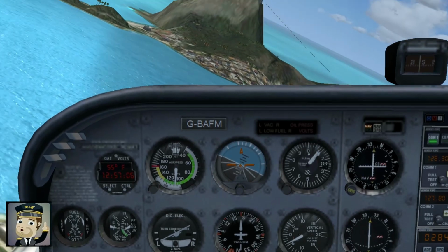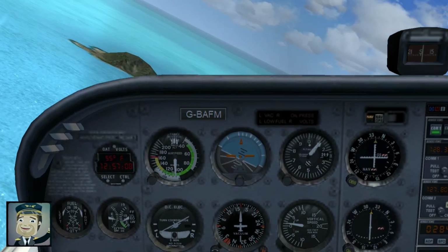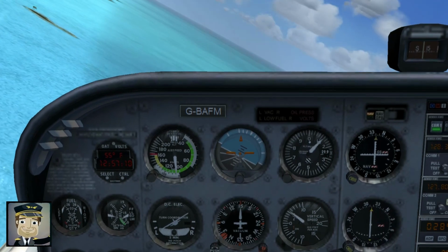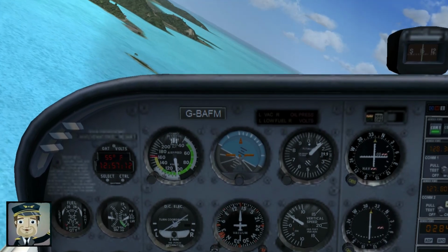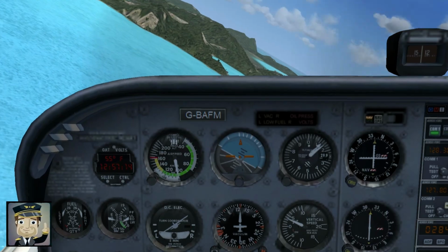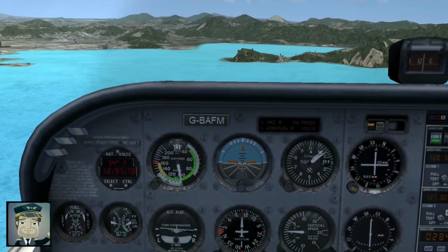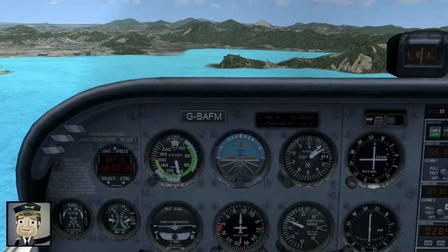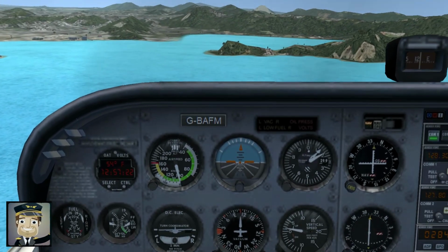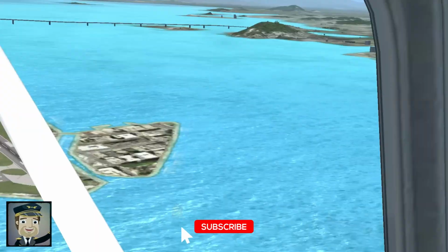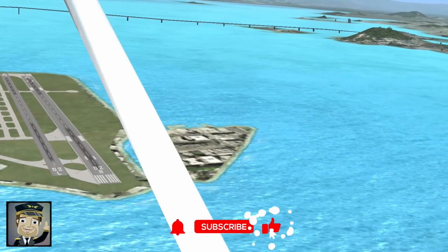So the pilot initiates a gentle left turn to enter the crosswind leg. Here, the aircraft flies perpendicular to the runway, gaining horizontal separation while continuing the climb. This segment is where the wind's lateral force becomes more apparent, often pushing the aircraft sideways. The pilot must apply drift correction to maintain a straight track over the ground.